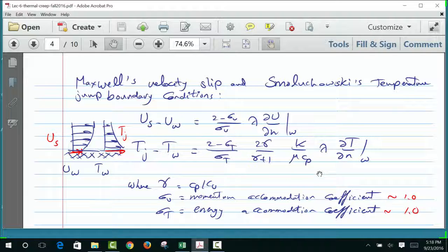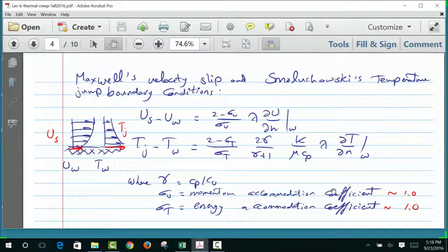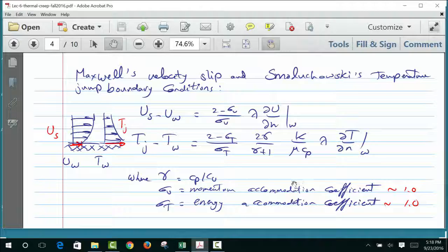Prandtl does this translation. He's like Google Translate. You give him English, he gives you French. You give him the temperature, he gives you the velocity. You give him the Reynolds number, he gives you the Nusselt number. It's how the energy diffuses and how the momentum diffuses. It's the ratio: divide by rho and divide by rho, you get mu over rho, which becomes nu, and rho Cp over K, that's the alpha.